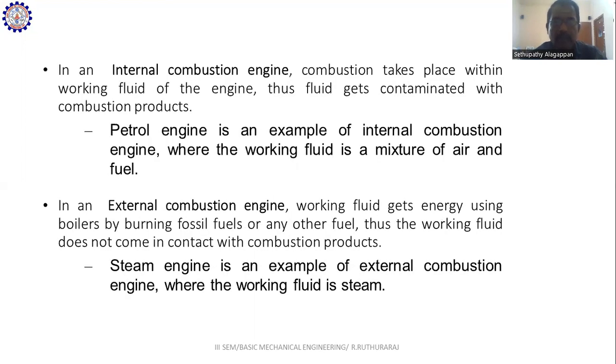In an internal combustion engine, combustion takes place within the working fluid of the engine. Thus, the fluid gets contaminated with combustion products. For example, a petrol engine is an internal combustion engine where the working fluid is a mixture of air and fuel, the petrol and air mixture. The combustion takes place inside the cylinder, so we call it an internal combustion engine.